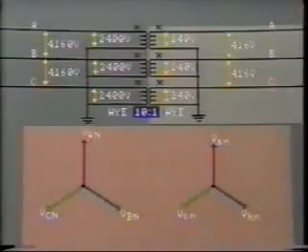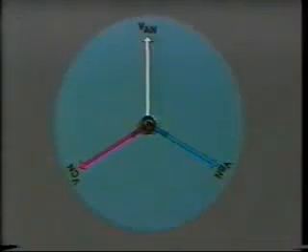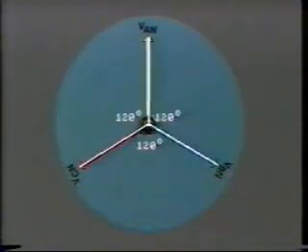In the last segment, during our discussion on polarity, we looked at the voltage relationships between three interconnected single-phase transformers. You'll remember this circuit diagram, but in order to understand this, it was necessary to also study the diagrammatic representation of the phase relationships between the various voltages on both primary and secondary side. This diagram is known as a phasor diagram. It shows the magnitude and the phase relationship between the various voltages in the system.